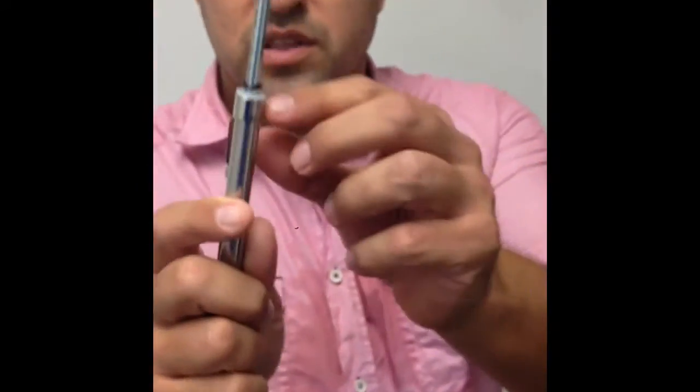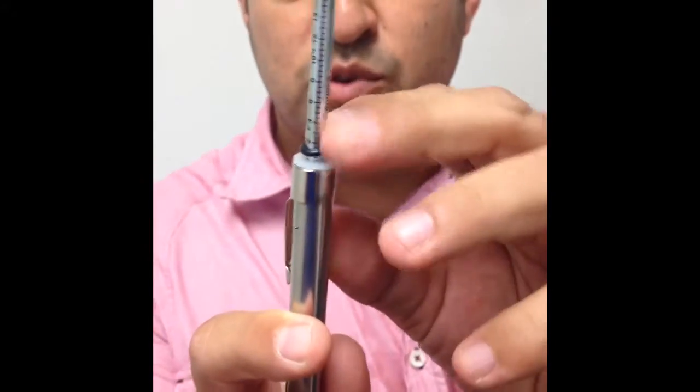To measure the door pressure, we would have to have the door closed. We would take our door pressure gauge. There is a little ring that we pull all the way down to the bottom. We'll go to the approximate location where you open the door naturally, and you will start pushing the door until it gives. That is your reading for the door pressure.